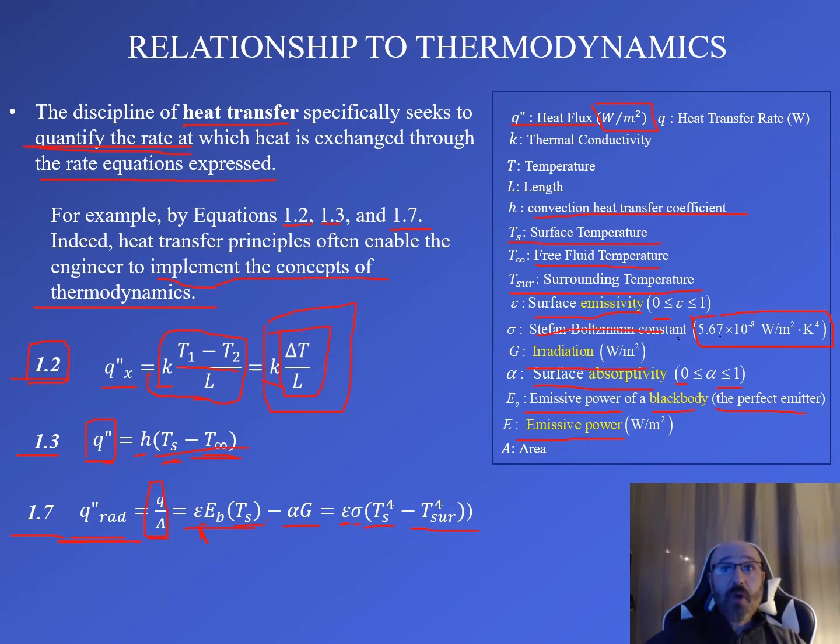And we can go through all of these, take a look at the corresponding units for everything, and make sure they double check. And with things like this where you're talking about length and temperature, are you putting those in the right units? Are you using meters, inches, centimeters? Are you using degrees Celsius, degrees Fahrenheit? What are the units you're using for each individual variable within this? Plug it in, double check, do out your unit analysis, and make sure everything works out as you would expect it to. So that's a great way to double check your work. One, to make sure you didn't miss plugging in anything, and two, to make sure you are using the right units.